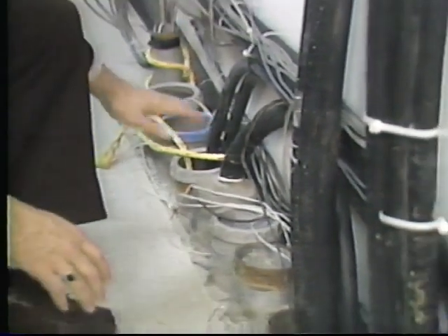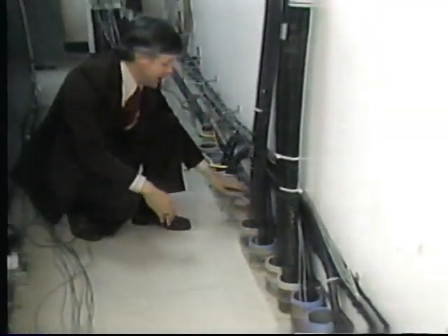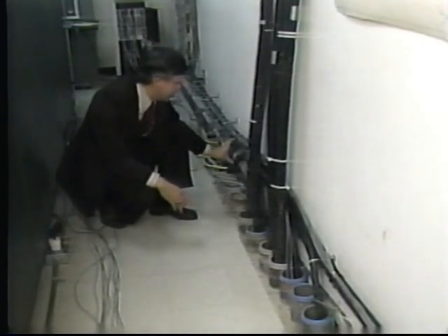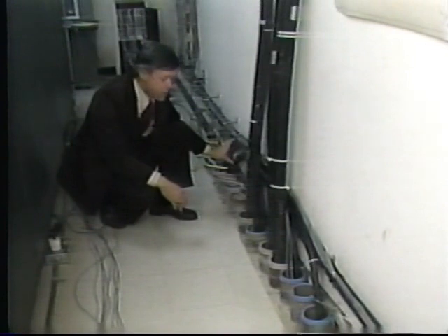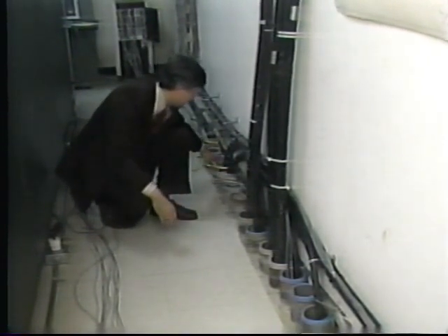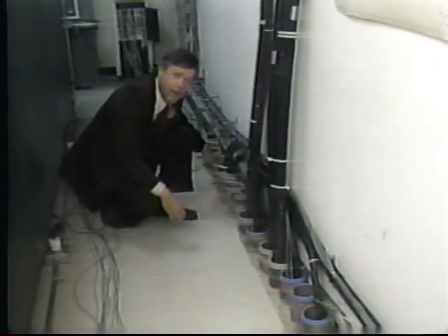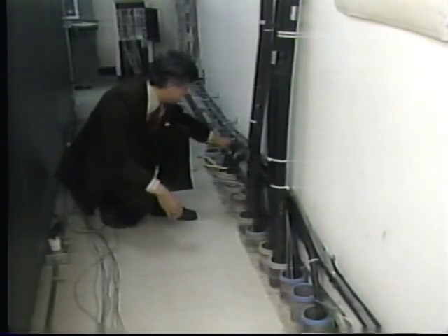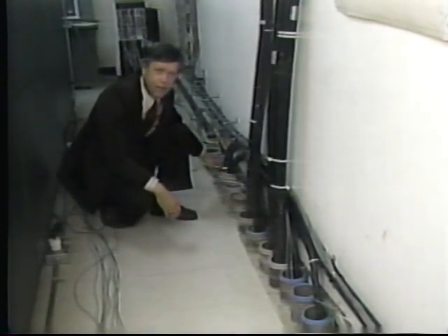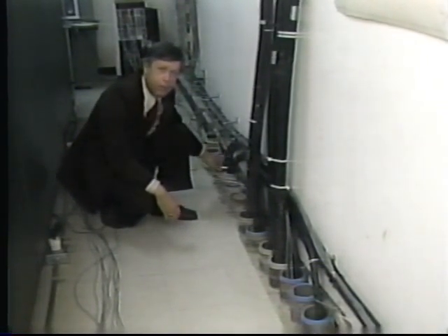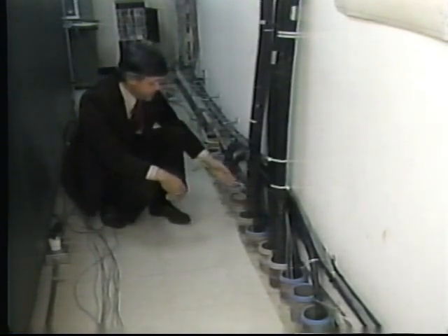Here at Spectrophysics, we're looking at the building access facilities. These pipes run back out to the street, and there where, in this local area, Bell System brings in their cables to supply the telephone lines to Spectrophysics. Now, not all the pipes are in use, and in some cases, like here, they've left a pull cable made out of a nylon rope that allows them to pull in extra cable. Since these two cables did not use the entire diameter of the pipe, by pulling in a nylon rope like this with the two cables, it enables them to pull in additional facilities at a later date.